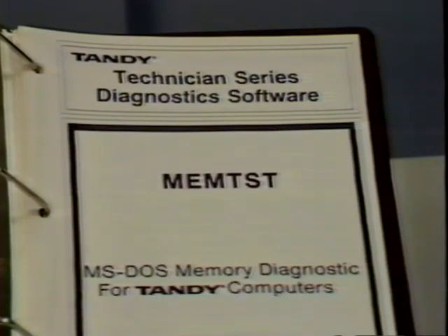Memory diagnostics of some type are available for most Tandy computers. The basic purpose of these programs is to write a specific byte of data into RAM, read it back, and verify that the data returned is the same as the data written. There are several varieties of RAM test, each of which exercises the memory in a different way. There is no single test that checks for all possible RAM failures. The time involved would be prohibitive.